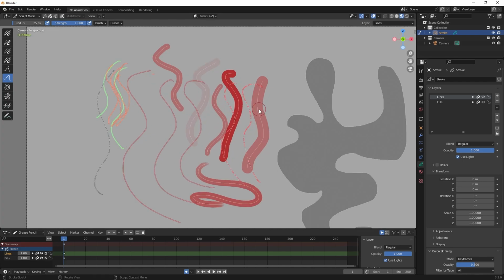I'll click it. So in sculpt mode, I have some tools that allow me to affect the vertices that make up grease pencil objects. So on the left, you can see I have some tool options. The first one is smooth. I'm going to click it. Then I want to drag over a stroke in the viewport, and you can see it smoothing that out. And I can go over it multiple times to smooth it even more. There's also one called grab. I'll click that. Left click and pull, and you see I can manipulate these strokes.